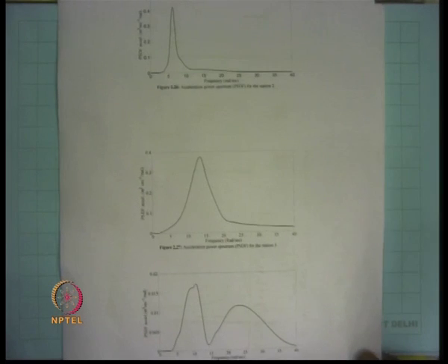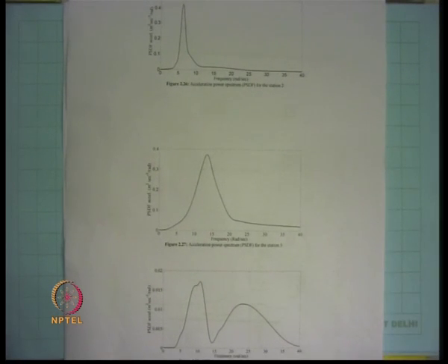Now, these power spectral density functions are available for the surface of the ground, and as I told you, if we have the information available on the surface of the ground, then many a time we have to do a deconvolution technique to obtain the corresponding quantity at the rock bed level, and then only we take that particular rock bed level information and we assume that the same condition exists at the rock bed of the particular site.